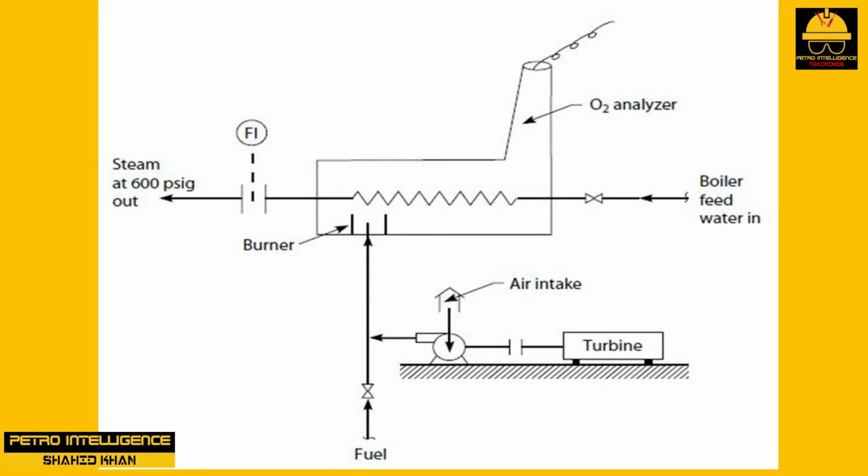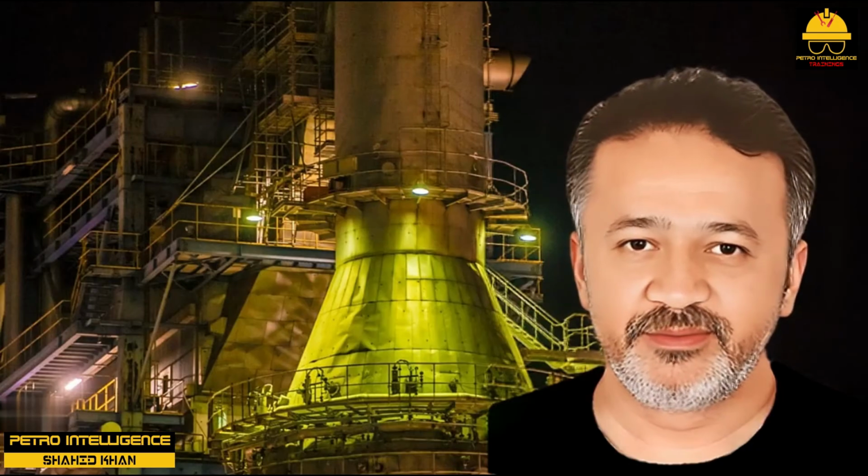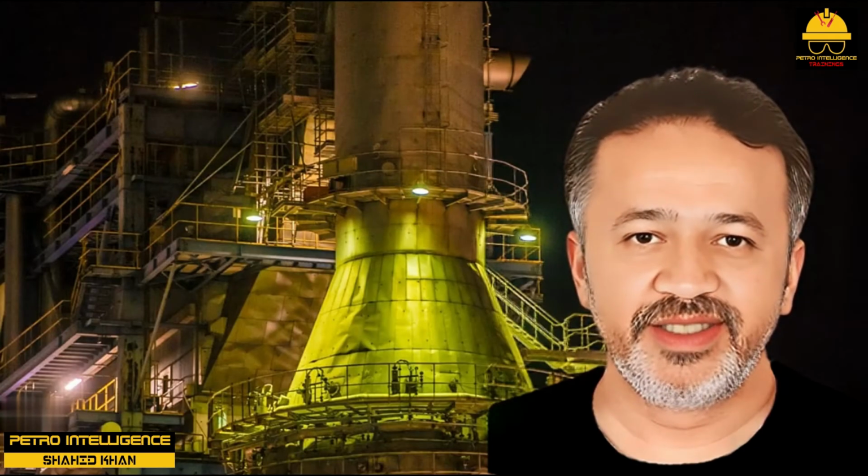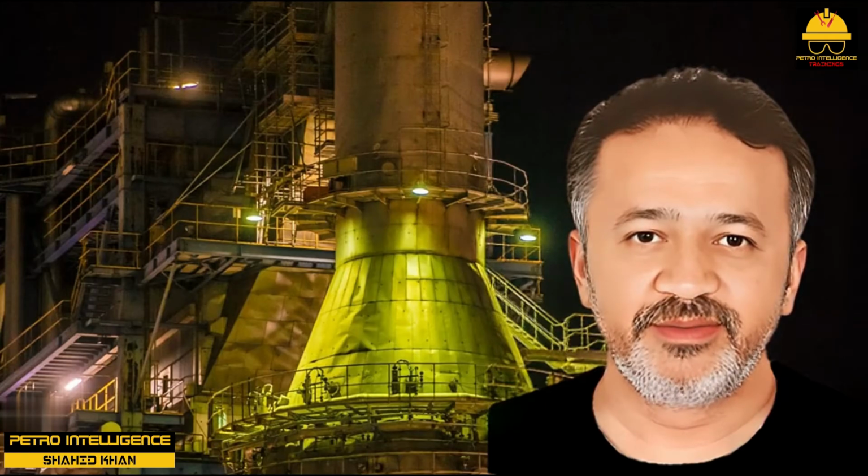The point at which the steam production is at maximum is the point of absolute combustion. The oxygen content of the flue gas at the point of absolute combustion, where steam production is maximum for a given amount of fuel, will be the optimum. It will not necessarily be at 2% O2 or any other fixed oxygen content. The oxygen content of the flue gas at the point of absolute combustion is a variable, depending on air-fuel mixing efficiency. The term absolute combustion is not the same as complete combustion.